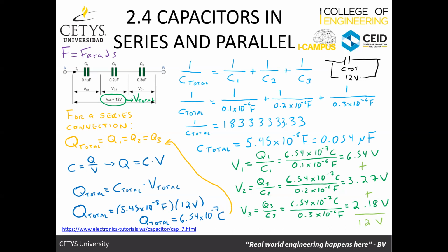In series, the total capacitance is going to be smaller than the individual ones. Parallel is the other way. Even I get confused sometimes because with resistance it's the other way around, and inductance is also the other way. So thank you for the clarification. In series, the total is smaller than the individual ones, and that way I can make a smaller capacitance value from an array of capacitors.